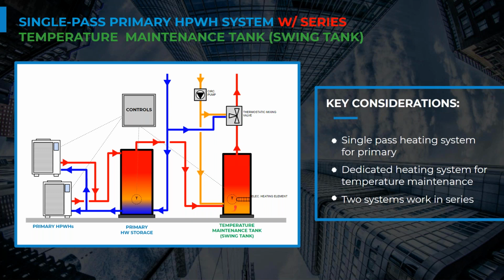So those two streams mix together, that maybe 110 degree water and that 150, and so that keeps it above about 125 degrees Fahrenheit. And so during a lot of use, we're getting a lot of energy transfer, and so this tank is often around 140 degrees Fahrenheit, or 10 degrees below what it's coming out here. And then during no use or low use, the temperature in this tank drifts down because we're not getting as much energy from that primary storage tank.